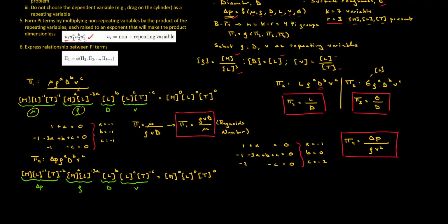Now this should make sense, right? Recall from our study of Bernoulli's equation. Remember, Bernoulli's equation states that we have a static pressure plus a dynamic pressure plus a hydrostatic pressure, which is constant along a streamline. And look at our denominator here, rho v squared. It looks a lot like the dynamic pressure that appears in Bernoulli's, right? It has dimensions of pressure.